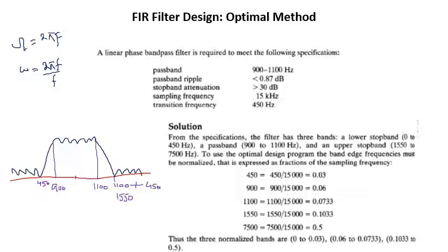So I hope that's straightforward. Okay, and again you understand, because of sampling the continuous time signal, in time domain, sampling results into replicas of this in the frequency domain. So again we have another replica here around 1. Okay, this whole thing, similarly we'll have another replica of this one around -1, and so on.